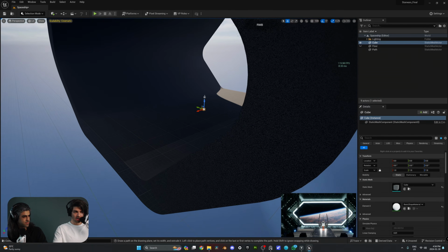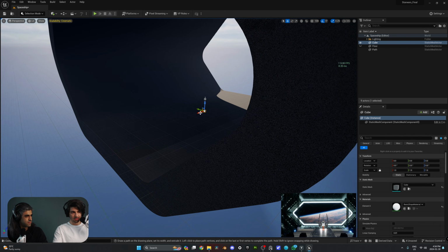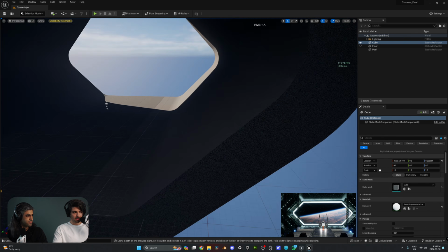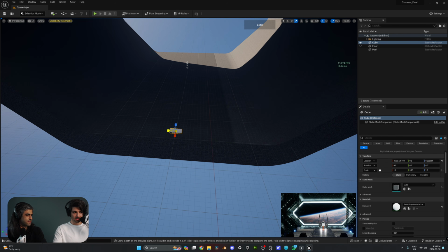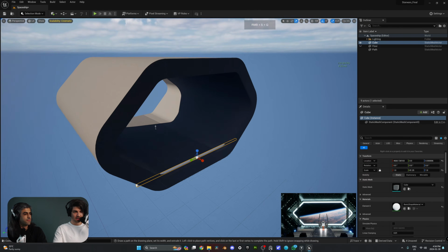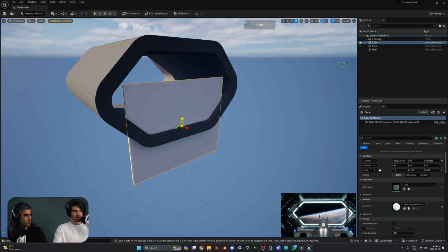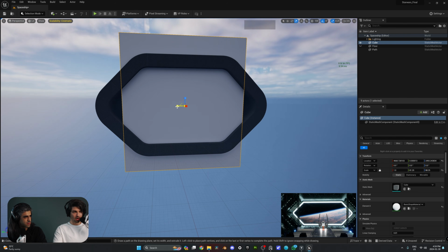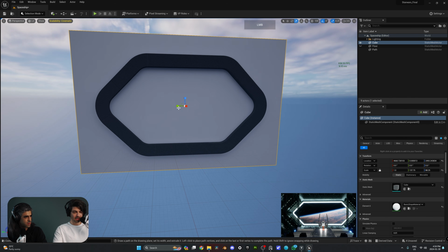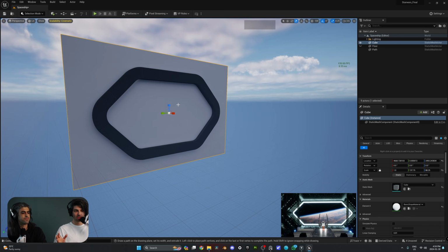So now we're going to move back. We're going to use the W key to bring out our transform gizmo, and then bring it all the way to the back here. And then we're going to go to R for scale, and make it big. So drag one axis. Perfect. Then we're going to drag the Z axis all the way. Perfect. And then we're going to go to W, move this up, right? A little bit more on the x-axis. And then we're going to just move it up so that it's somewhere in the middle. And then we're going to go back to R, and then we're going to scale it on this axis. So I made it big enough, Farhad, just so that I know it's covering everything, you know? No light leaks.